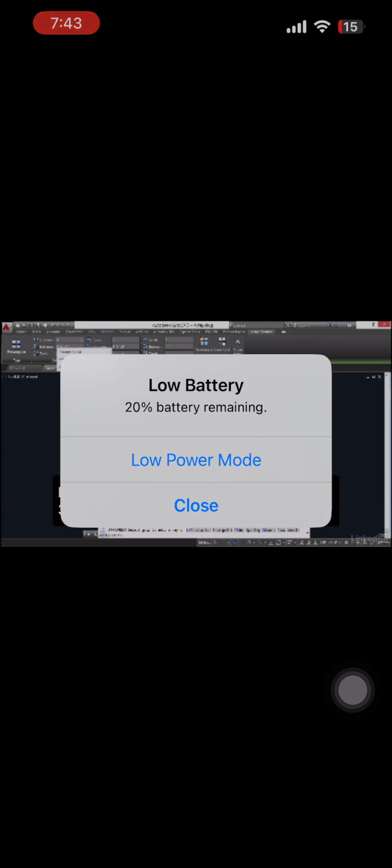Highlight the value here and change it to 3. Press the Tab key to have it take effect. Sometimes it takes a couple of seconds before it updates. The number of rows should be 1. So type 1 and press Tab. You can set the distance between the columns here. So right now it's at 3 foot and 1/2 inch. I'll change that to 2 foot 6 by typing 2'6, press Tab to have that take effect.